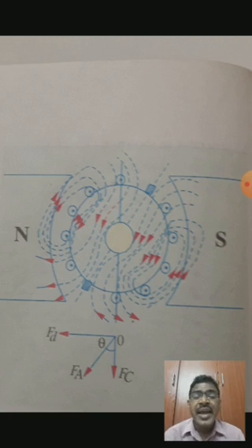The demagnetizing component will reduce the flux available in the DC generator. Hence it reduces the EMF induced in the DC generator, since it is directly proportional to the magnetic flux. The next component FC, the cross magnetizing component, will distort the magnetic flux in the air gap between the armature and the field coils.